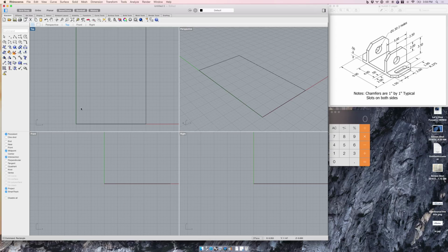So the first one is in a distance of 1.5 in, so I'm going to go in 1.5 and draw myself a guideline. If you hit enter, it'll just repeat the last command, which was a line for me. So those are guidelines, and then the center goes up 1 inch. So we'll go here and draw another guideline. So now these intersections are where my circles are going to go.